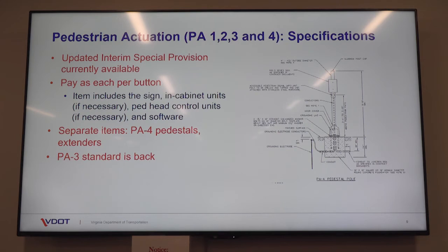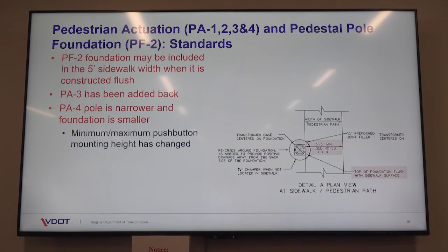It creates a conflict with the 1 foot standard because we're not supposed to have anything within 1 foot of a sidewalk. Shared use space even more. It's 2 feet, 3 feet, and it's all described with the standards, pretty much reflections of federal standards and AASHTO. So yeah, we'll definitely have to look into that and get back to you on that. Okay, that sounds good. Thank you.